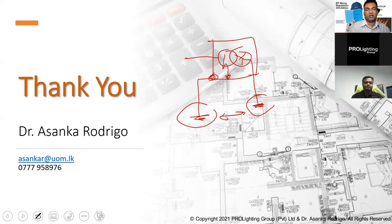The other possibility is where you connect them together. In that case, depending on your electrode resistance, there will be a voltage that can transfer to the low voltage side. But in both cases, you have to calculate the high voltage fault current as well as the low voltage fault current, IF2 and IF1, and check what the fault current is. Based on that fault current, you can size these conductors.